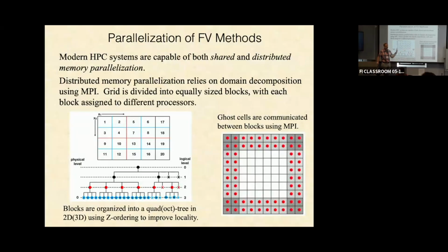It will be related to refinement in just a second, because the Octree is really needed for mesh refinement. If you're only doing uniform meshes, then you don't really need Octrees. You could just use these Cartesian grids or some other way. But as soon as you have AMR, then you don't really have a choice except to have some kind of more advanced way of storing. Honestly, Octrees is such a common data structure in computer science, so I think there's even classes which implement this for you automatically. We rolled our own in Athena++ because we wanted the smallest Octrees possible.